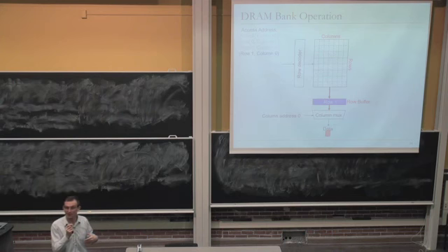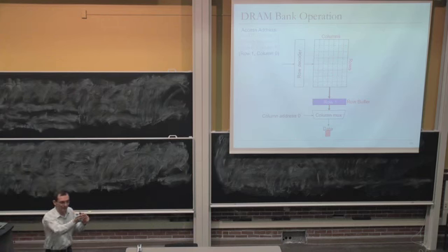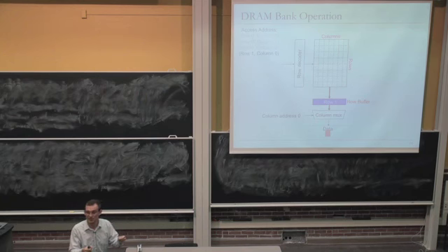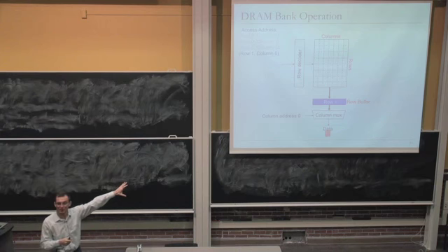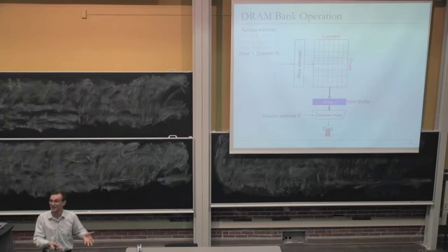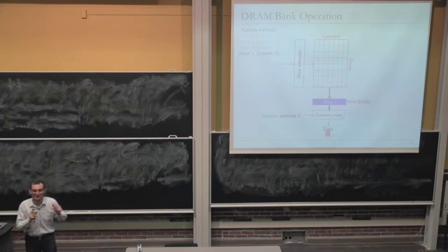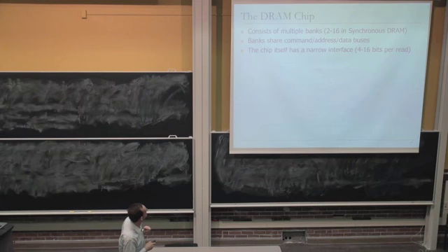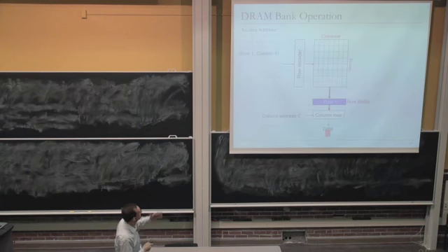Remember, these rows lose charge over time. And one of the jobs of the DRAM controller is to refresh these rows so that you don't lose data. And Ameya's point is essentially that these refreshes interfere with normal operation, right? The controller needs to ensure that not only normal operation goes on, not only processor requests are satisfied, but also the data is kept intact in DRAM. So now we have one complication. We'll see a lot more complications in DRAM soon. Okay, so that's the operation.